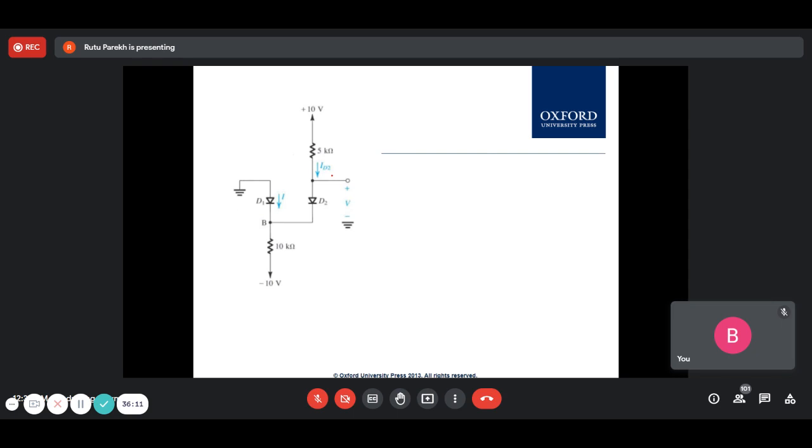So as an engineer, what we do is we suppose, because we don't know which of the four conditions holds. If both are not conducting, it means the circuit is dead, and we don't need to do anything. So you are left with three suppositions. Either one of them conducting is two suppositions: D1 is conducting and D2 is off, and vice versa. And the third supposition is both are conducting. With that supposition, you find I and V. So here you can do two things, especially if you find I, the direction, you know where is I now here.